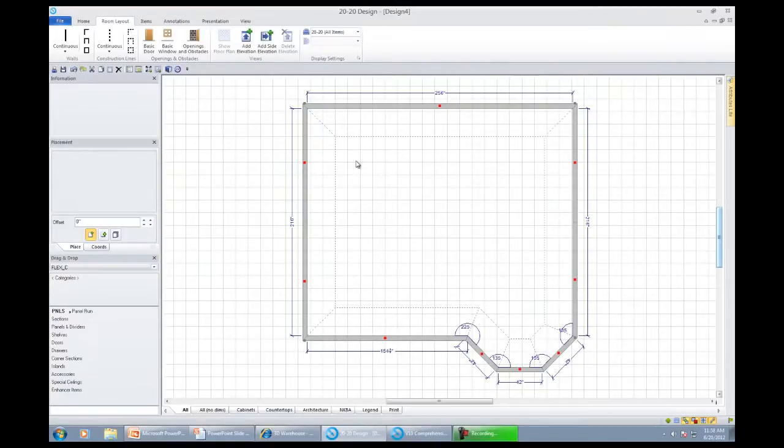Once you point the direction, all you have to do on the keyboard then is let go of the mouse, type in the length, hit Enter, takes you directly to the next wall. You can draw walls in a snap now. The next feature I want to talk about, though, is how do you adjust the heights of the walls. This has changed significantly in version 10.